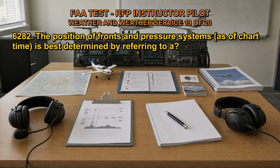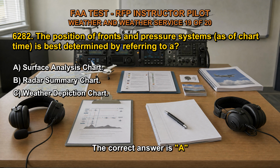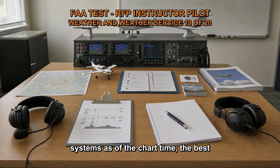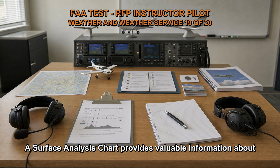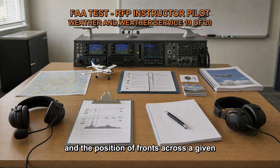6282. The position of fronts and pressure systems, as of chart time, is best determined by referring to A. Surface analysis chart, B. Radar summary chart, C. Weather depiction chart. The correct answer is A. To determine the position of fronts and pressure systems as of the chart time, the best reference is a surface analysis chart. A surface analysis chart provides valuable information about atmospheric pressure patterns, the location of weather systems, and the position of fronts across a given region.